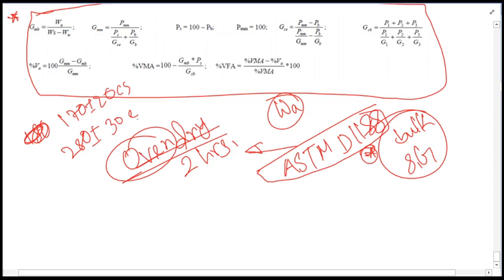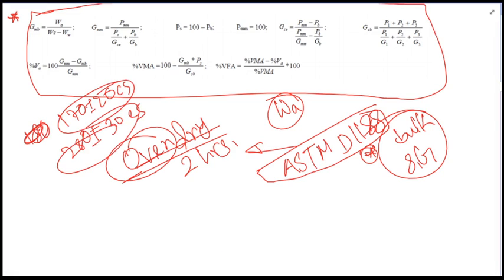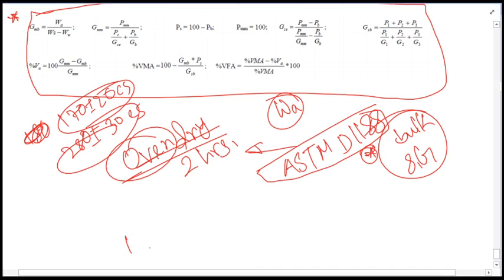This centistoke corresponding temperature, say if I make it easier for you, from the log graph I have shown you, as I can remember, you might have got the temperature for mixing maybe 148 to 153.